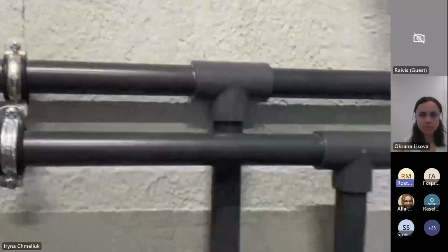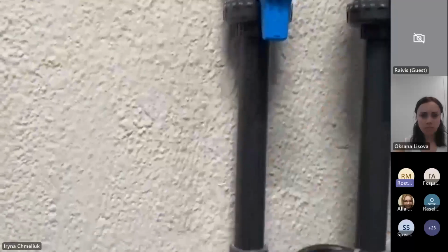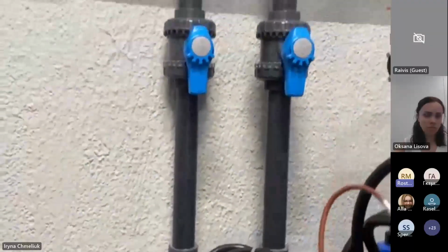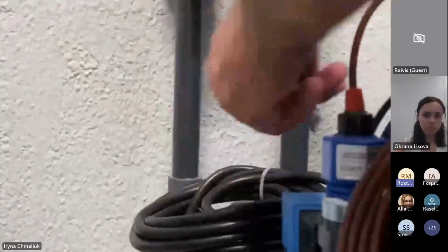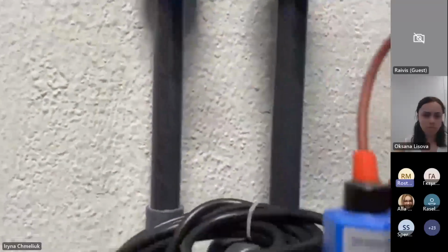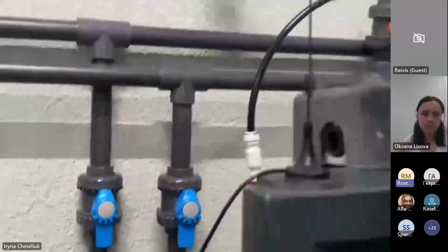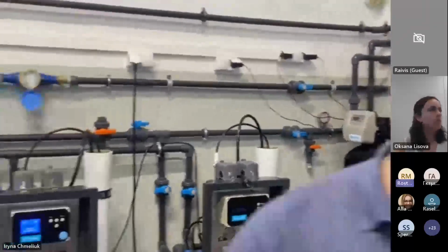First of all, I would like to draw your attention to the piping and how it is done. As you may see, the connections are made with 1-inch pipes. This is a sufficient pipe size to provide enough water with low pressure loss. We have 1-inch on the water supply, drain, and the permeate. With this type of connection, we can ensure the right operation of the system. This is how we should connect the units.